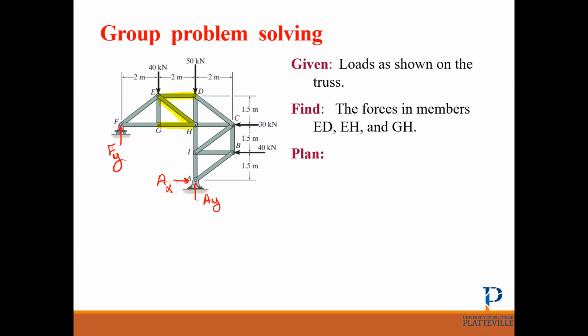So now you can tell me where is the best cut for this truss. Excellent. The best cut is from where we have all these internal loads. So here is the best cut. It's only 3 members. We have 3 equations we can solve, and also it's where we need this internal load.